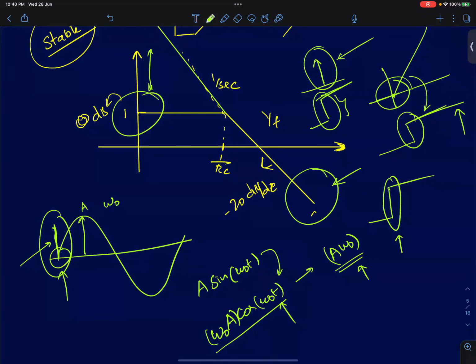Even an impulse function, in the steady state, is zero, which means there is no change. And for a ramp function, even though the ramp is changing, it depends on the slope, but the second derivative is zero. Only the first derivative is finite, and even the first derivative is not changing. So all these responses in the steady state become low frequency inputs.